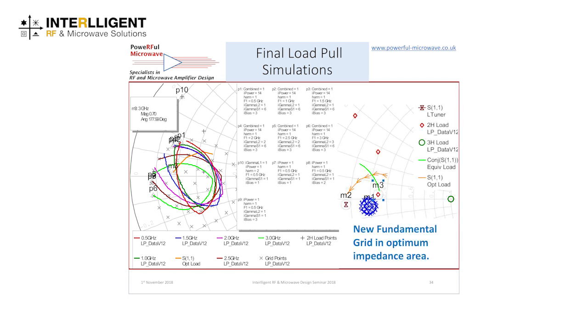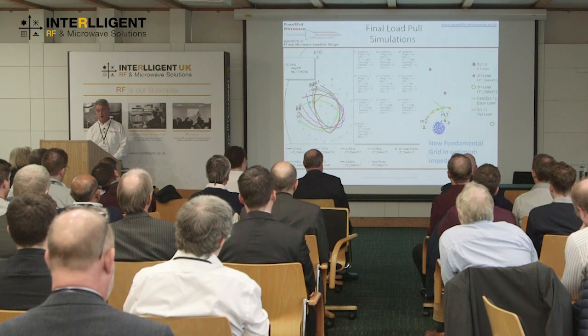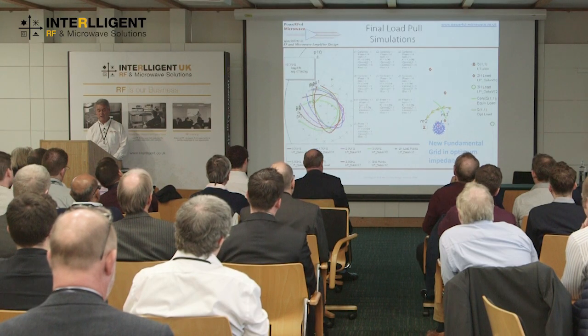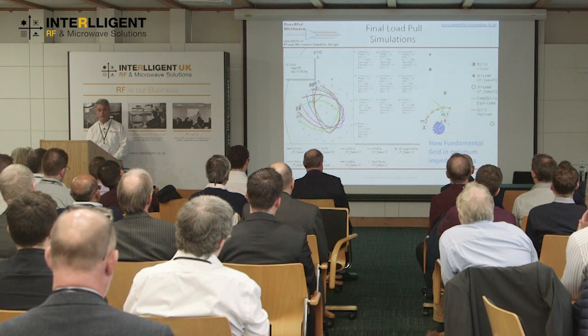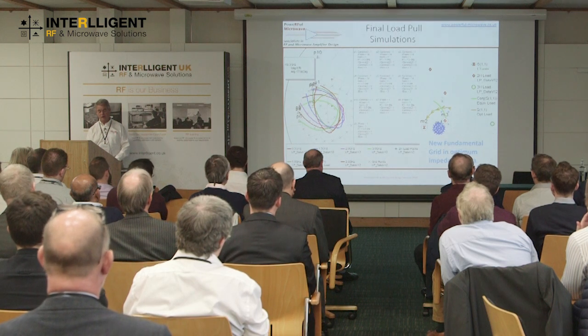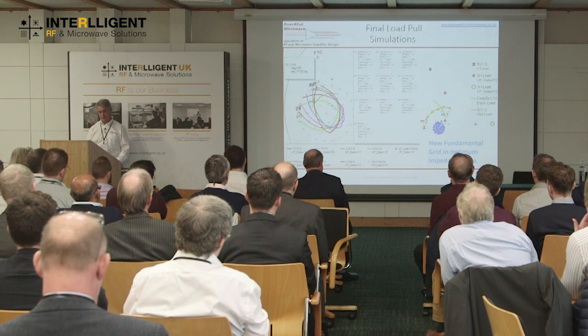So now what I'm going to do is vary the load impedance around a lot of points around this optimum, so somewhere within this circle we've determined, and we're going to step the harmonics. We're going to keep them near the center of this and then move out towards the edge, which is a more likely response that we're going to get with a matching circuit.